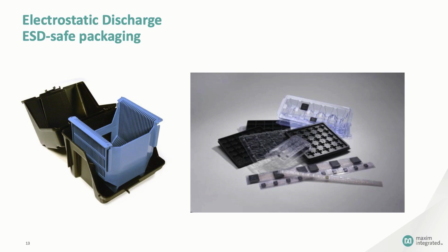Static dissipative or conductive materials, on the other hand, do protect the contents from static discharge. Anti-static material is often pink in color, while static dissipative materials are often black or dark and appear metallic, frequently because they do include a thin metallic layer. But be careful, not every black or metallic-looking material is static dissipative. Look for a logo or other indication on the package before you use it.